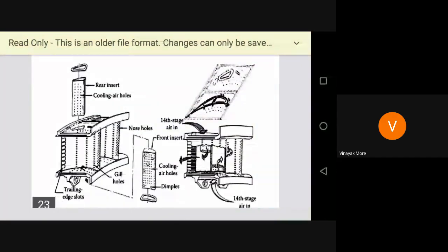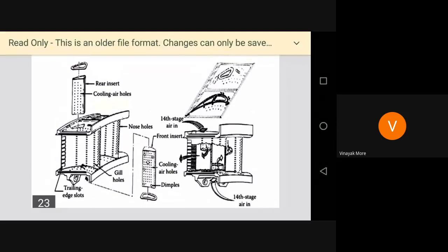So here you can observe the nozzle guide vane cooling passages. It's very important. This is the stator. So before combustible gases are inletted towards the turbine or the rotor blades, there we supply the gases in a given direction to hit the moving blades. So that is called a stator or the nozzle guide vane. This is going to act as a nozzle, which is a reaction turbine here. So this stator is the first step where the high temperature gas is going to impinge on the nozzle guide vane.